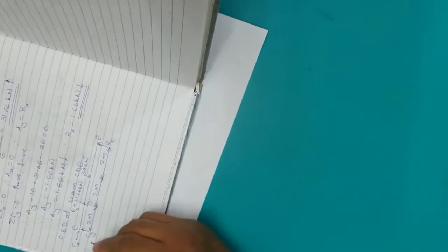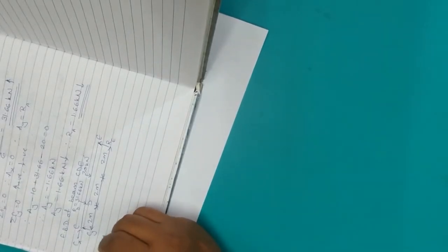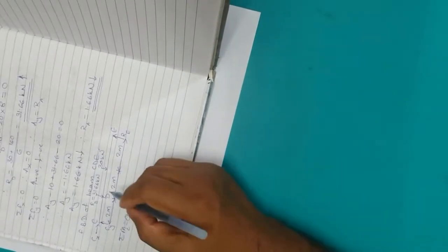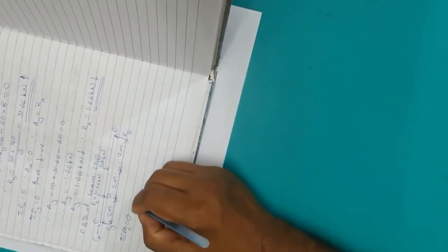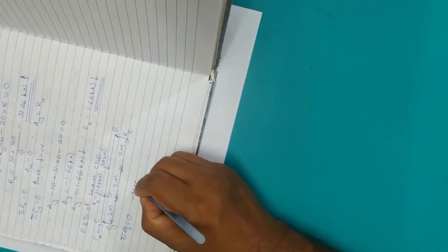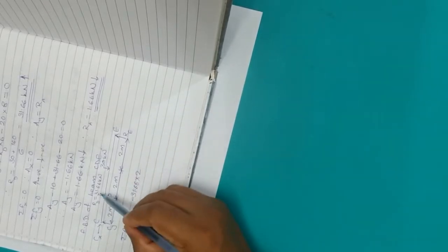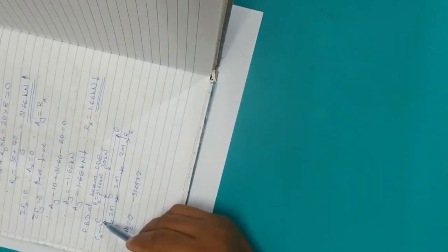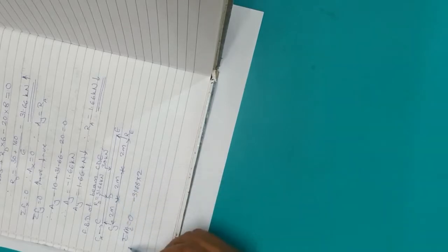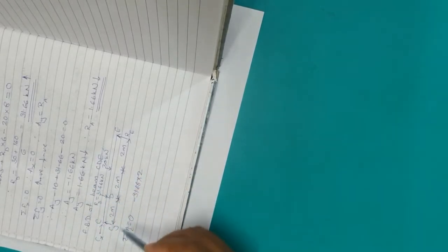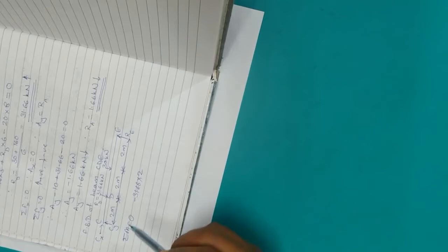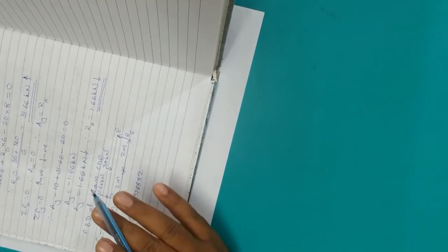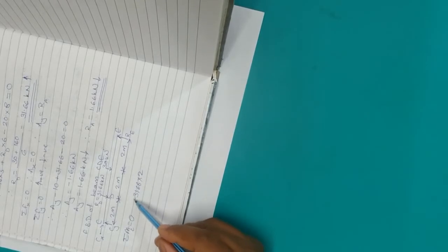As usual, let's apply condition of moment summation MC equals to 0 about the hinge point. Let's see then. Let's write minus 31.66 into 2. We have taken magnitude of the force and then we have multiplied by the perpendicular distance from point C, and we have checked the rotational sense. It is clockwise, that's why we have taken the minus sign. Remember, while calculating moment, direction of the force has no role in deciding sign of the moment.